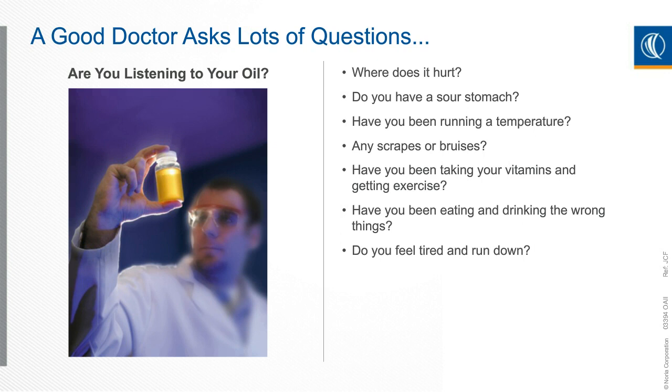Are there things your machine is experiencing right now that you see through oil level inspection, sight glass inspection, bottom sediment water bowls? Maybe the temperatures are different. Maybe you're hearing things differently. Maybe the vibrations are different. What's going on in your machine that can give you clues to figure out whether or not you need to adjust your oil analysis differently? Or if it's simply a routine oil analysis being performed, there will be standard tests that you may want to run so that you can trend data over time to give you quality results.